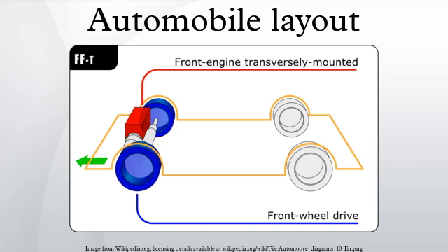Better braking. The more even weight distribution helps prevent lock-up from the rear wheels becoming unloaded under heavy braking. Towing. Rear-wheel drive puts the wheels which are pulling the load closer to the point where a trailer articulates, helping steering, especially for large loads. Serviceability. Drivetrain components on a rear-wheel drive vehicle are modular and do not involve packing as many parts into as small a space as does front-wheel drive, thus requiring less disassembly or specialized tools in order to service the vehicle.